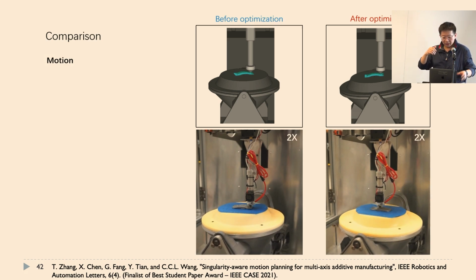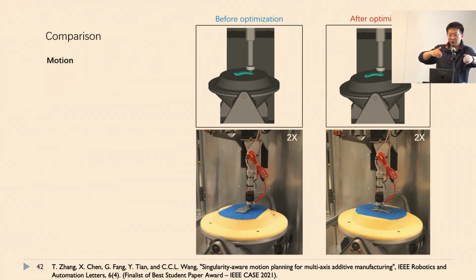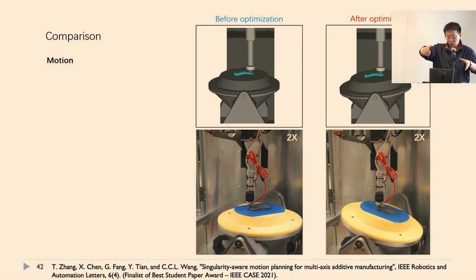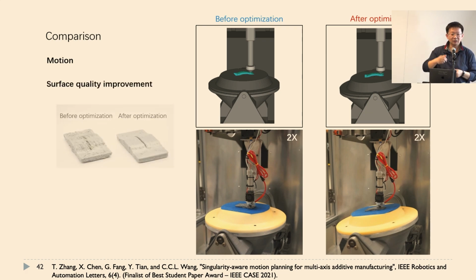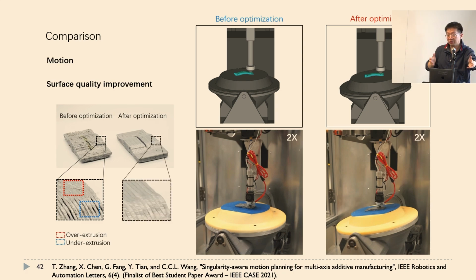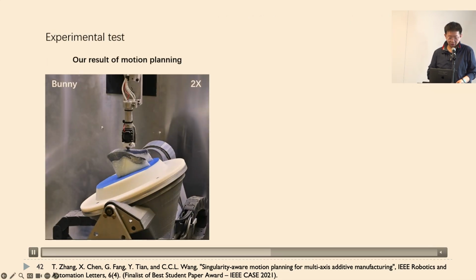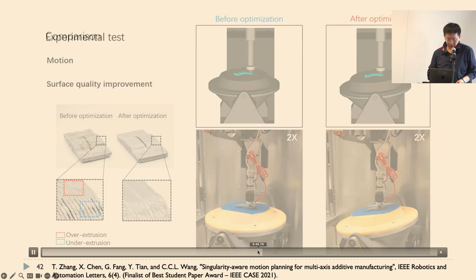And then the problem is, when your rotation is not fast enough, don't forget you are really working with two machines. One machine is this moving stage. The other machine is the extruder, the material extruder. And the material extruder is not well synchronized with this rotation. So it turns out the insufficient rotation causes the problem, as I can show here on this image.